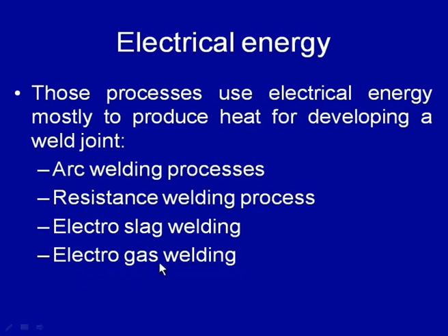Similarly, in case of the electrogas welding process, heat required for melting the faying surfaces and filler material is obtained by establishing the arc between the consumable electrode and the weld pool. So, here the arc is well covered by inert or inactive gases to protect the weld pool from atmospheric contamination.